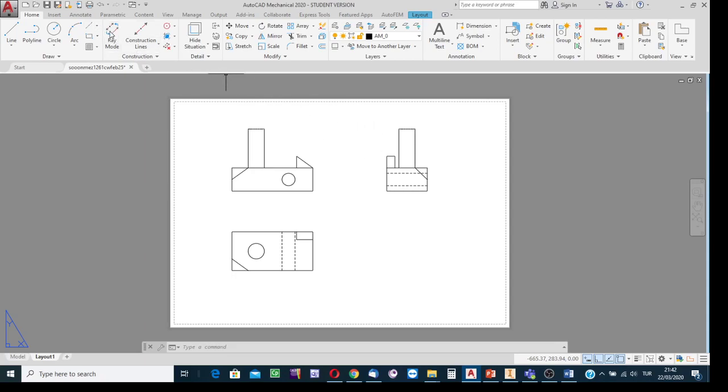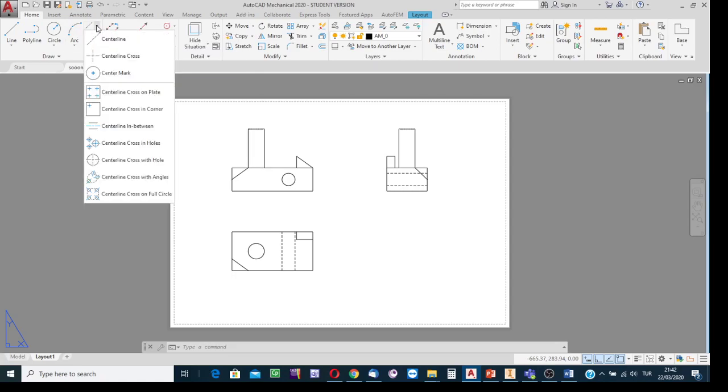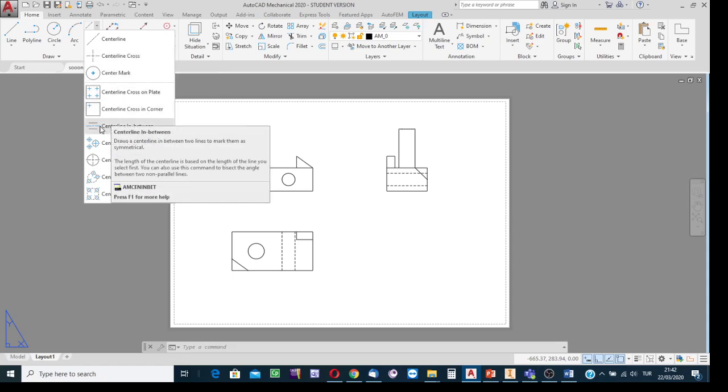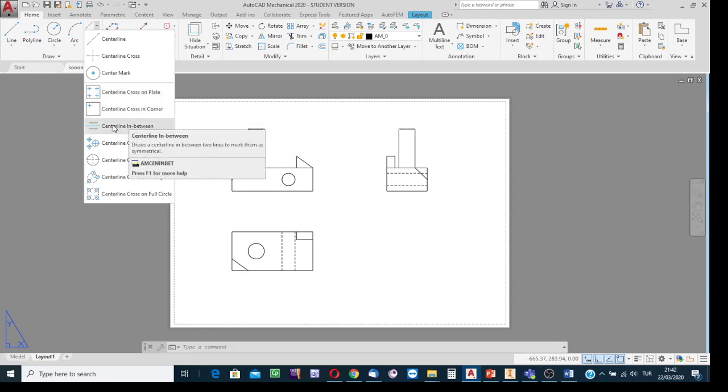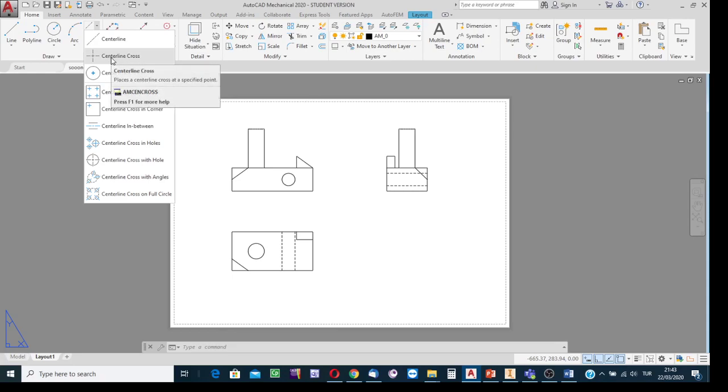And then for the symmetry axis, we use in the two-dimensional environment this tool in the drawing panel, the symmetry axis creation tool. For creating horizontal and vertical axes, use this facility. For creating a longitudinal axis, use that facility. But this facility is applicable for having a longitudinal axis if the views have been drafted once, not created. But the center cross option is applicable if this facility is going to be used for the first time,